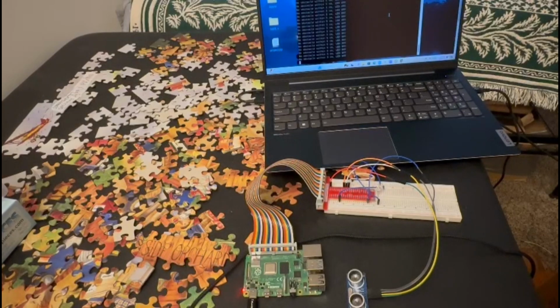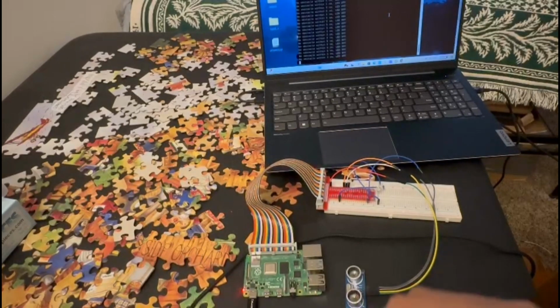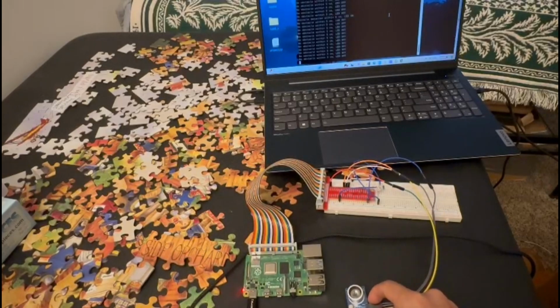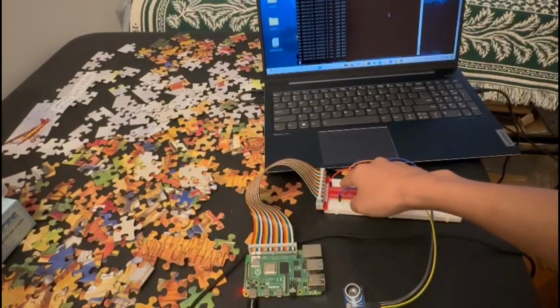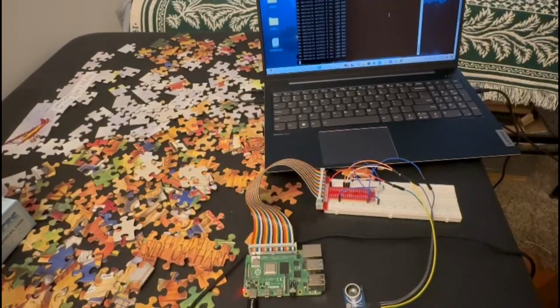Today, we are exploring a very exciting and simple setup between Raspberry Pi, ultrasonic sensor, and LED. This is our ultrasonic sensor, which has two important pins here, trigger and echo. Trigger emits the sound wave, which is eventually going to be received by echo. These two pins are connected here in Raspberry Pi GPIO 24 and 23.